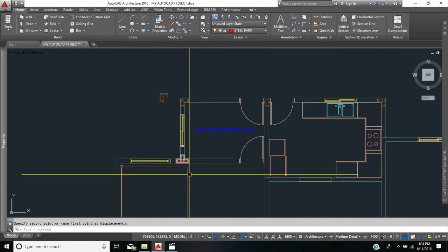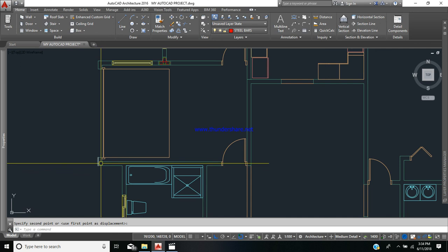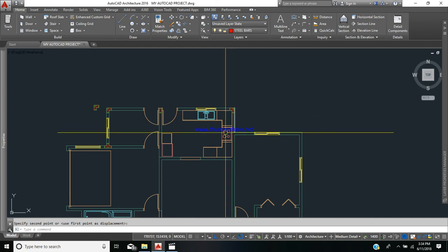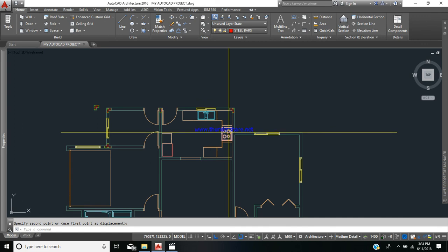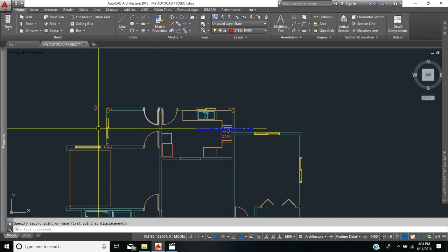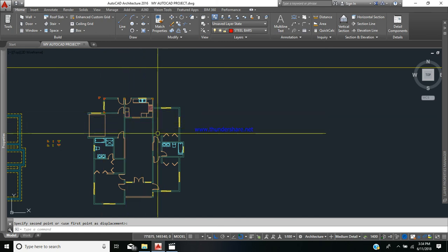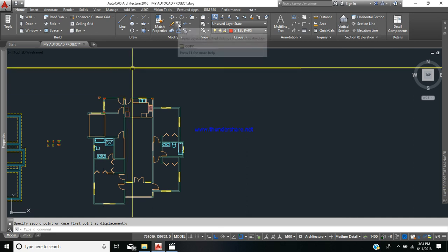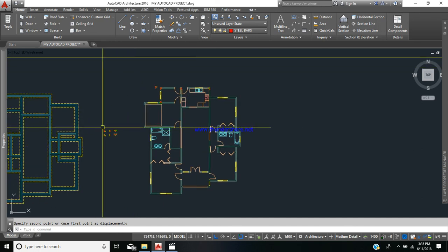Alright. Likewise, we would have gone around the building and found appropriate placement for stiffeners. This will be discussed individually based on the stiffener placement that you would have come up with. Having placed your stiffeners in your floor plan, and you would have waited until you have completed the entire building placing in your stiffeners, then you would have just now gone about copying your stiffeners from your floor plan onto your foundation plan.